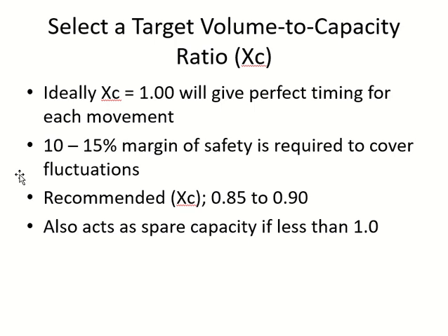Okay, clear? So previously we were talking about the V by S ratio, and here we are talking about the V by C ratio. Again combined for all the approaches: total volume upon total capacity of the intersection, not lane group. It's not for lane group, it's total. And you have to decide.